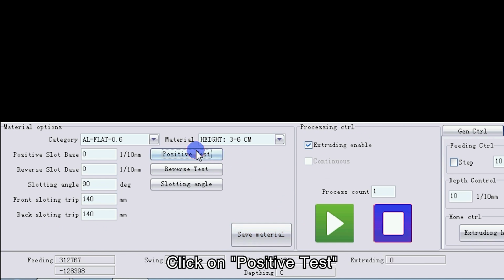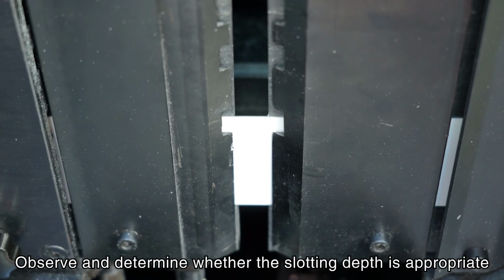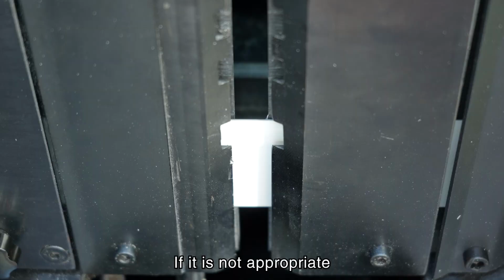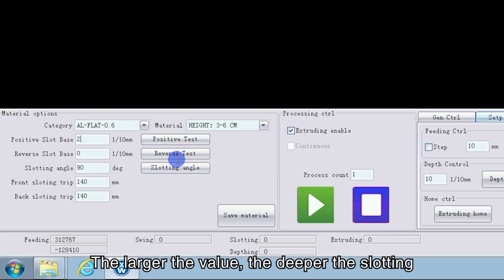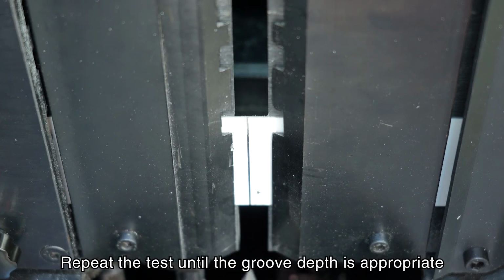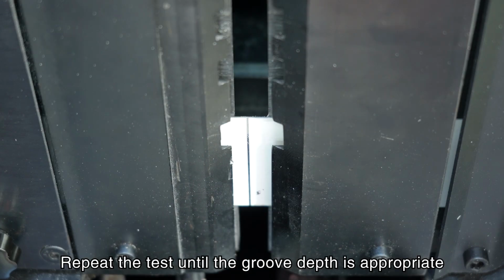Click on Positive Test. Observe and determine whether the slotting depth is appropriate. If it is not appropriate, change the positive slot base. The larger the value, the deeper the slotting; the smaller the number, the shallower the slotting. Repeat the test until the groove depth is appropriate.